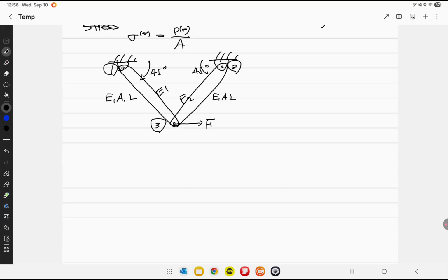Now, is that how you define the element? No, that's not enough. You need to define nodes of the element. So that one bar element has how many nodes? 2, right? So element 1 has node 1 and 3. Why not 3 and 1? What's wrong with the 3 and 1? It can be either depending on your coordinate system. But you need to make up your mind. Once you make up your mind, it's your freedom to choose 1 and 3 or 3 and 1. But once you choose it, you need to stay on it. That's the key point. Don't change your mind. So I will choose 1 and 3. Why is it important? Because the choice of first and second node determines what?